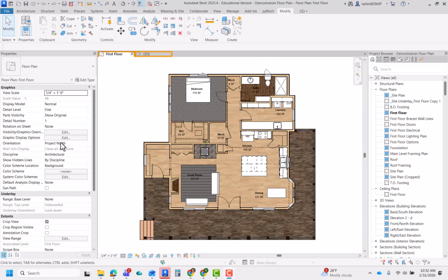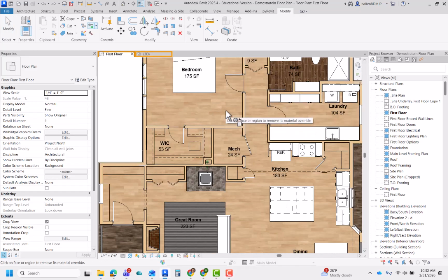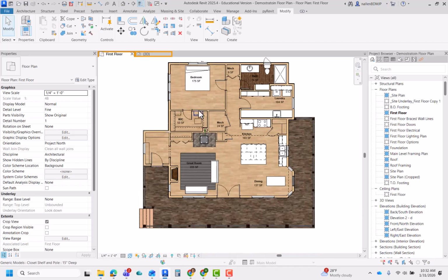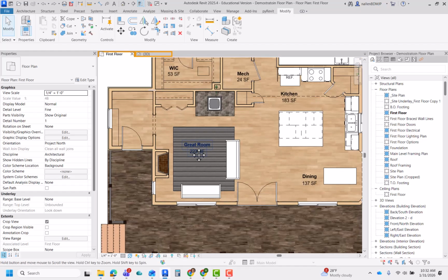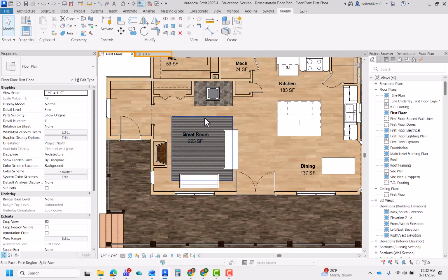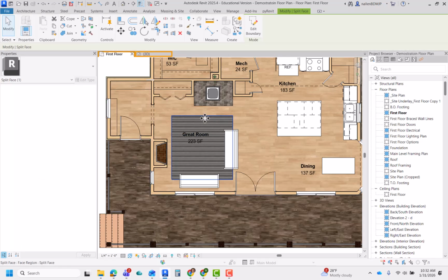If you apply material you don't like, there's two things you can do to fix it. One, you can go right back to the paint tool and you can click on Remove Paint, and that'll just return that floor back to whatever it was previously. And you could also, in a place like where you have the area rug, if you decide you don't like that, you can select it and you can just hit delete. You might even be able to move this thing around. So I can select that area rug, and with my arrow keys on my keyboard I'm just moving that back and forth.